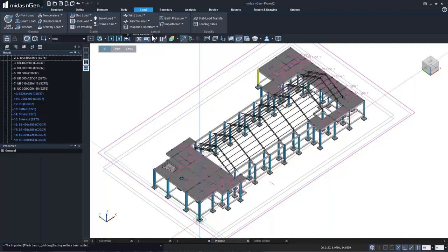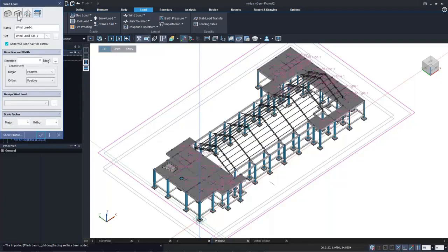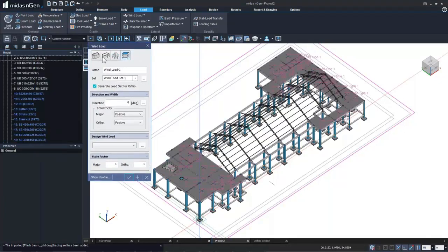workspace, and I'll go again to the assign wind load option, and here we have different options available, like we can have an enclosed area type of wind load definition, open area wind load definition. In case of silos, we can have an equipment type of wind load definition, or the most conventional one, that is the story type of wind load calculation. So we can select right now, for an example, the story. And we have the option to automatically generate different load cases by defining only once. So that's there.